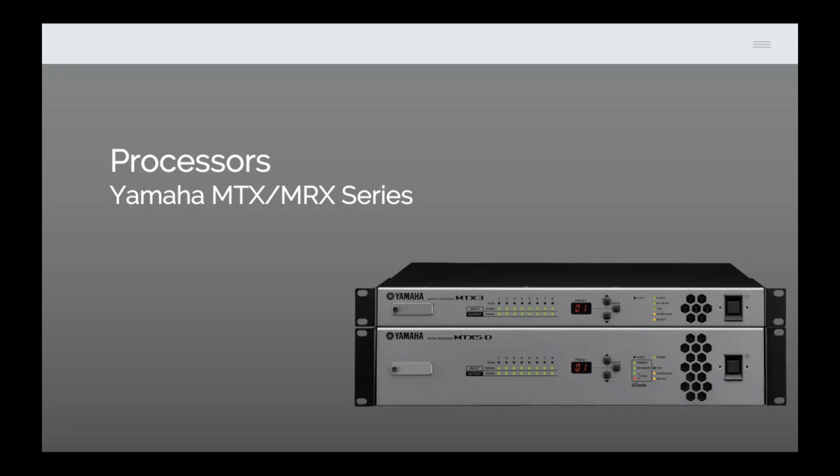In the application for subwoofers in a single room environment, then I would be inclined to use a bigger amplifier like the MRX series I'm just about to come on to, and use dedicated amplifier lines for the subs, because that's going to allow you to adjust the subwoofer level critically, proportional to the output level of the speakers, because the speakers are a kind of separate entity in that application.